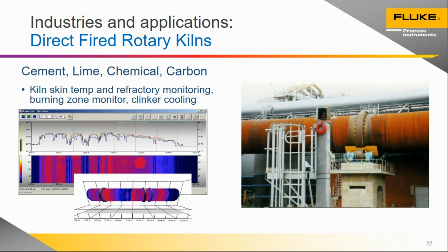The purpose of this, and I talked to a customer just this week who had experienced at their plant, which did not have a line scanner like this, a big problem in January where they were missing some of the refractory bricks. That breaks down on the inside, and they do periodic maintenance to inspect it and make sure that's in place. But in their case, they didn't have any early warning that this was taking place, and they were missing refractory in one spot and were overheating the kiln shell and ended up warping that kiln shell, which obviously can be a really expensive problem. So the goal mostly here is to make sure that you're protecting that kiln shell and that you don't have problems with your refractory.